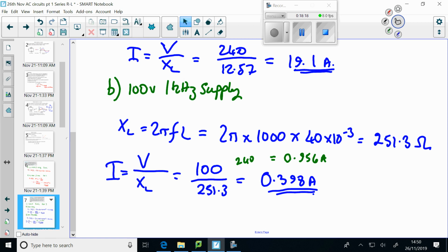I can give you a practical indication of the implications of the difference between impedance in an AC circuit and resistance in a DC circuit. I had some machines where I used to work that had little tiny plug-in relays. Some of them were a DC coil for a 24 volt DC solenoid, and some of them were for 24 volts AC. If you put an ohm meter on the coil of the DC coil relay, you'd measure somewhere around 50, 60, 70 ohms. If you put a DC meter on the AC coil, maybe about 3 or 4 ohms.